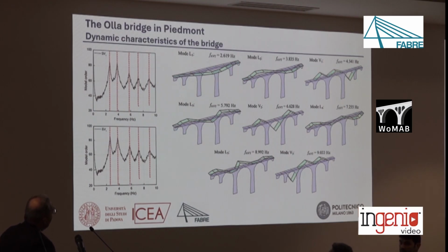Basically we collected information on five lateral modes of vibration and 3 vertical modes. The fundamental mode of vibration in the lateral direction had a frequency of 2.6 Hz, while the fundamental mode in the vertical direction has a frequency of about 4.5 Hz.